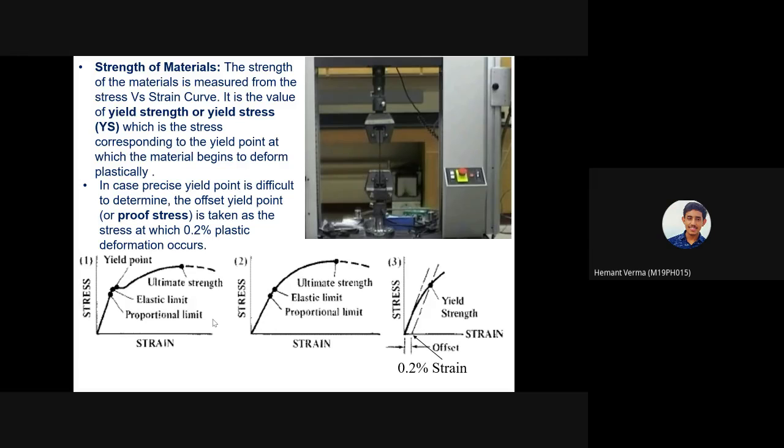Sir, my question is that in theoretical study, we give a strain like 2% strain to a material biaxially. Then how is it possible by experiments? Experiment will do a stress versus strain curve, a curve like that. Then you can measure this is the 0.2%, because suppose it failed here. That is the 100% strain. So it failed here, not at 100% strain. We calculate what the strain value is, that is considered as 100% strain, and then you come down here and find out what the 0.2% is. Okay, sir. Thank you.